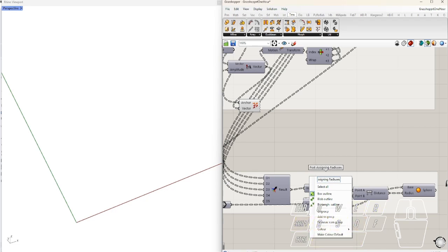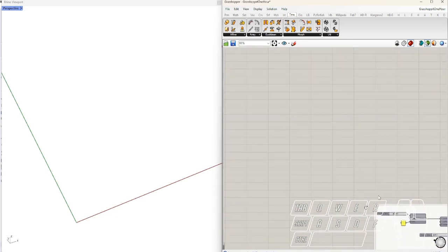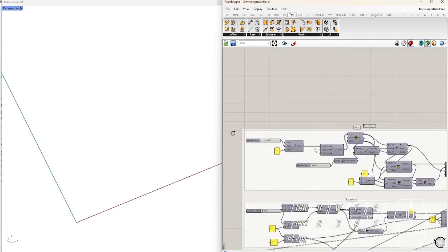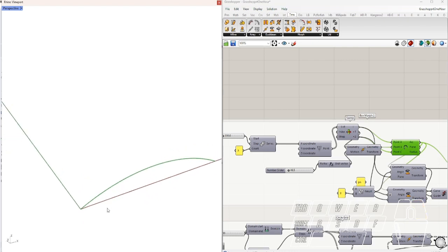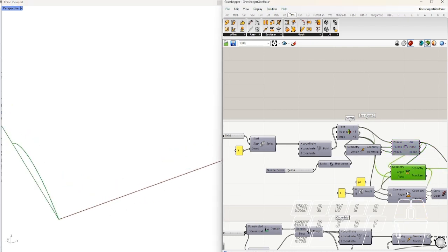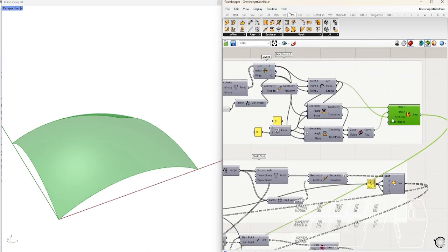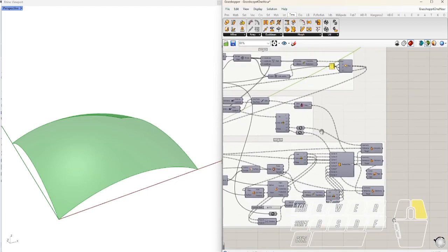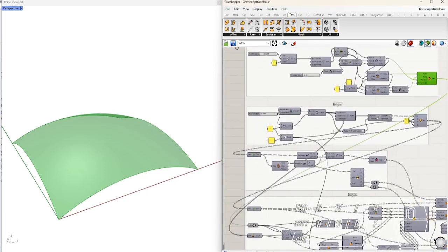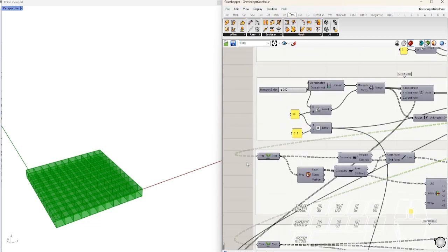Now we're going to try to morph other geometry, which is going to serve as an inner structure again, and make sure to preserve its geometry. So we prepare first the guiding or the reference boxes, and then we're going to use them to create the guide curves, basically.